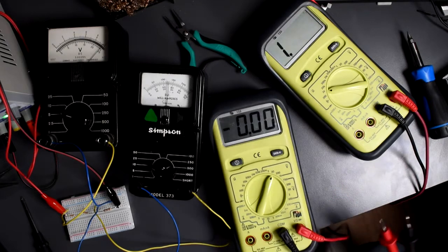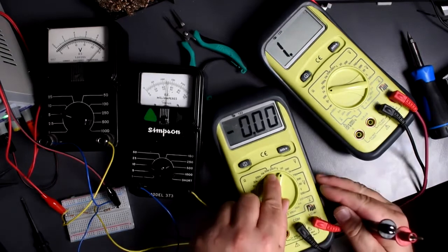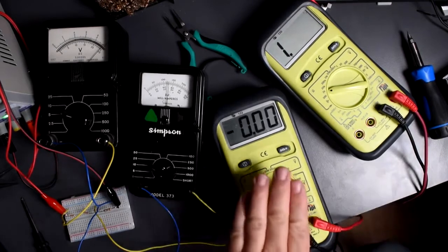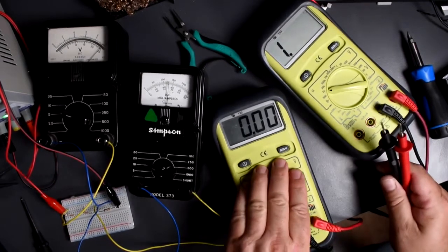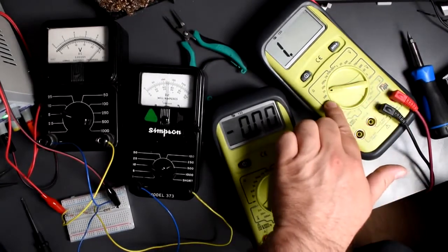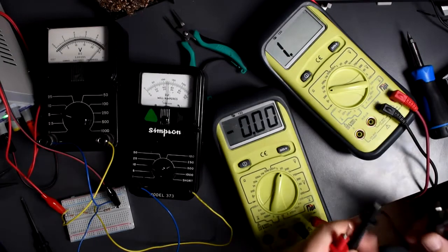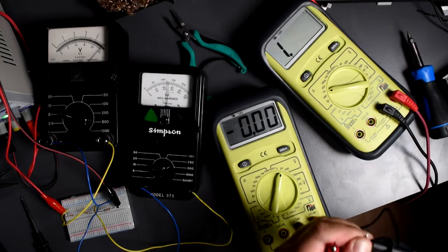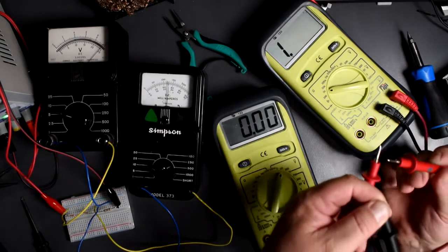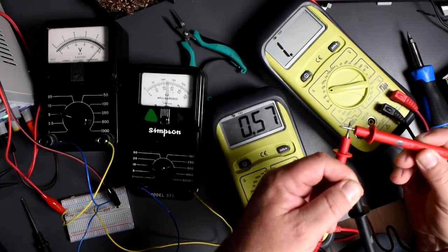Okay, now let's take a look at what is the voltage that this one. So the other multimeter, I have set it up as a voltmeter. So using this voltmeter, I'm going to measure the voltage across these 2 probes when it's configured as an ohm meter. So let's just take a look at that. I can hold this like that for now, but the other one, I'm just going to make sure that I'm not touching anything else here now.